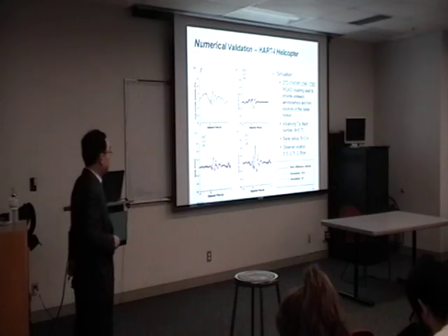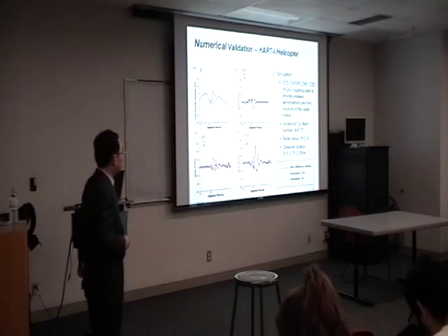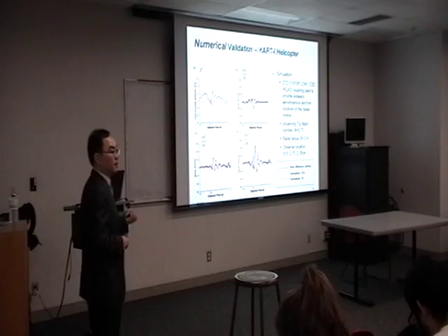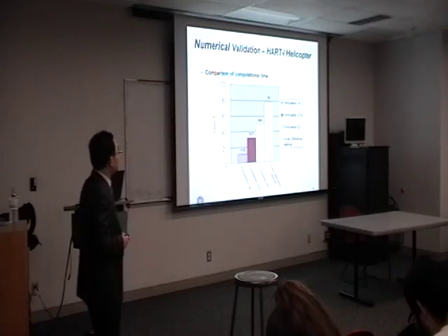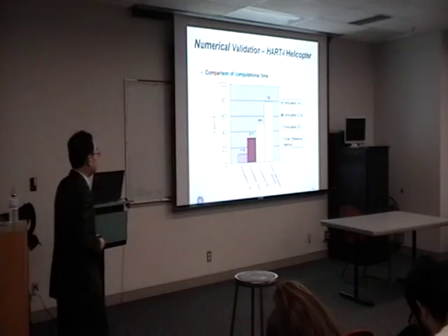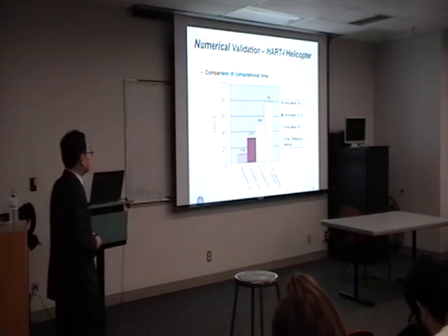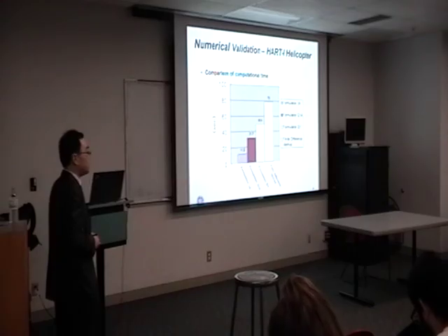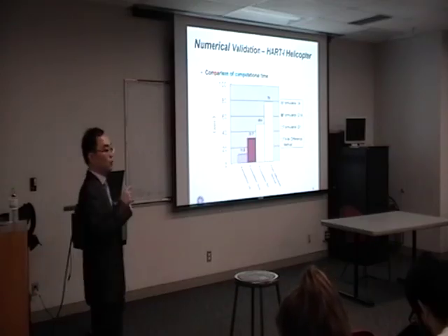So is there any benefit with this, because I'm getting the same solution? Yes, I have benefits. I look at the computation time. There's a huge difference. Formulation 1A is just for acoustic pressure, and these three terms give the pressure gradient. The same solution, but very different computation time. So formulation G1A, which is a purely analytic solution, reduces the computation time by a factor of more than 2 compared to the finite difference method, which is the gradient operator outside the integral.